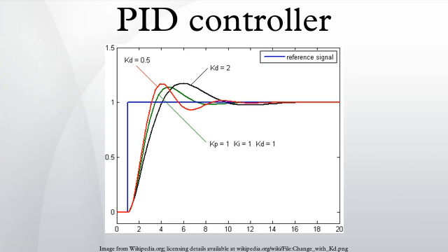The input to the process, and the output of the PID controller, is called the manipulated variable or the control variable. The difference between the temperature measurement and the set point is the error and quantifies whether the water in the container is too hot or too cold and by how much. After measuring the temperature, and then calculating the error, the controller decides how to set the tap position. The obvious method is proportional control. The tap position is set in proportion to the current error.